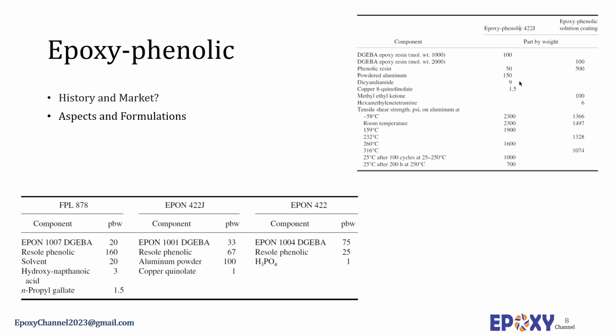The epoxy phenolic adhesives have moderately good peel strength, which is acceptable for many structural applications. However, the demands for high peel strength and high temperature adhesives such as aerospace honeycomb bonding have resulted in formulations with the addition of thermoplastic modifiers in the epoxy phenolic formulations.